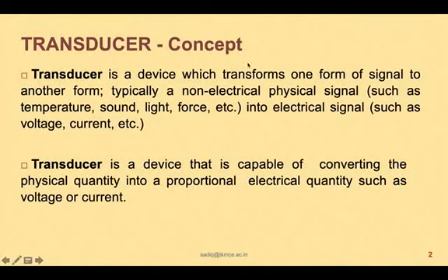A transducer is a device which transforms one form of signal to another form, typically a non-electrical physical signal such as temperature, sound, light, force, etc., which are converted into electrical signals such as voltage, current, etc. A transducer is a device that is capable of converting the physical quantity into a proportional electrical quantity such as voltage and current.